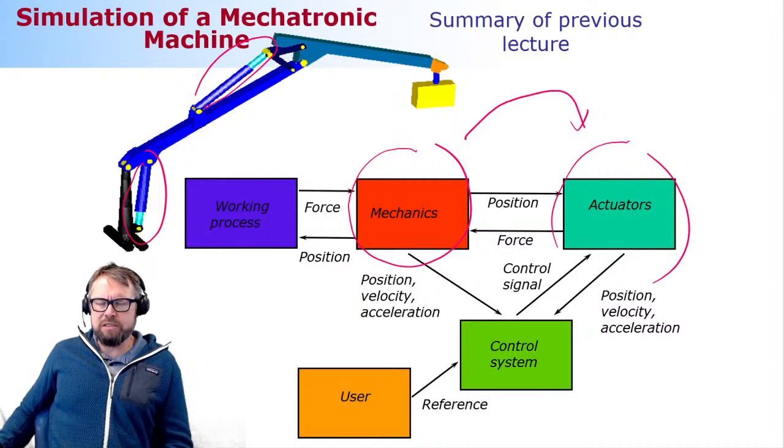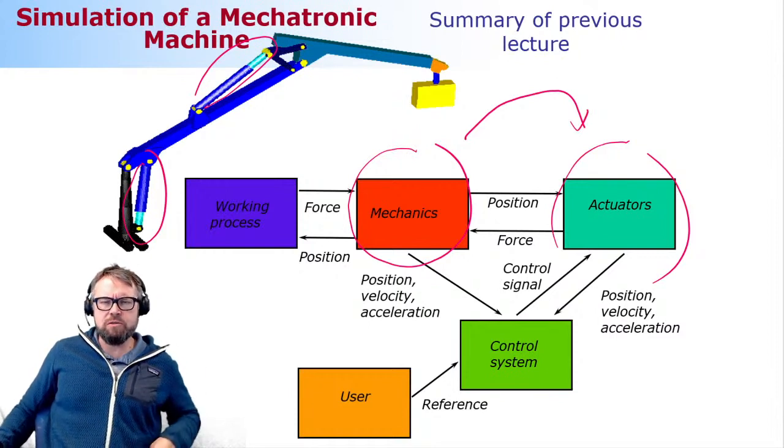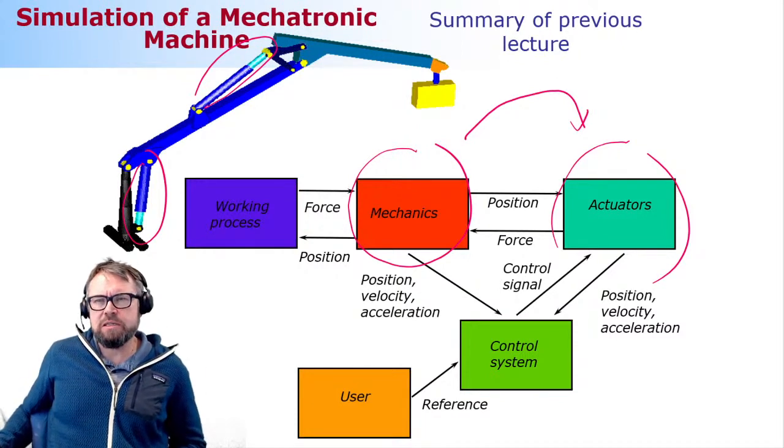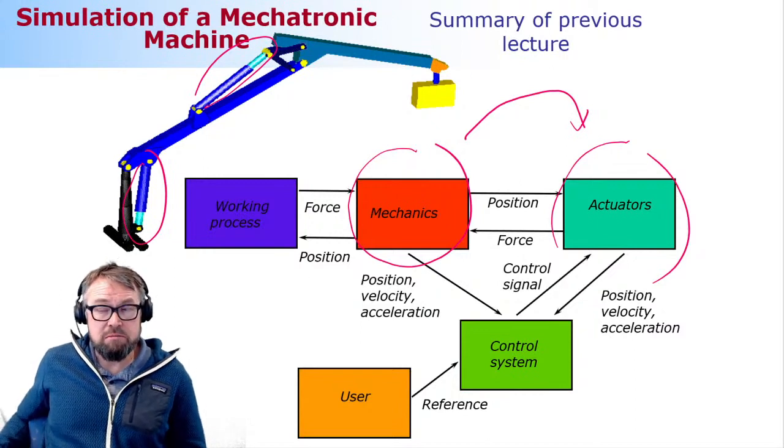The big picture is such that you're introducing pressure losses to control the hydraulics, which is a big problem because the pressure losses are energy losses as well. And we don't want to waste energy, like I said in the beginning. So the developments related to hydraulics are not significant. There is recently something that is interesting, a little bit promising too. It is called digital hydraulics. That I'm going to explain to you next week.